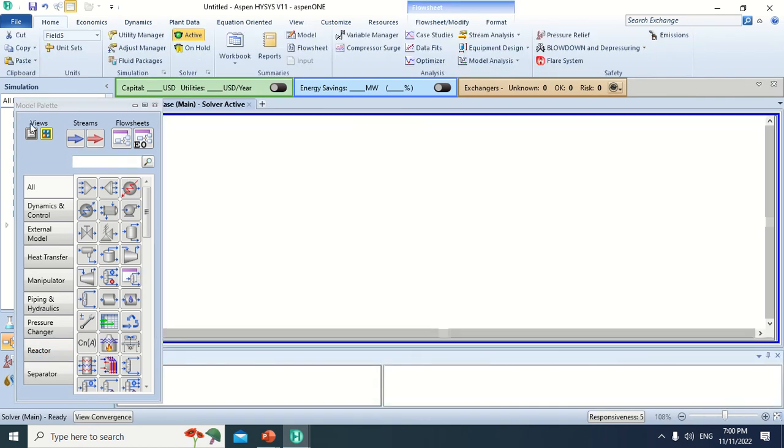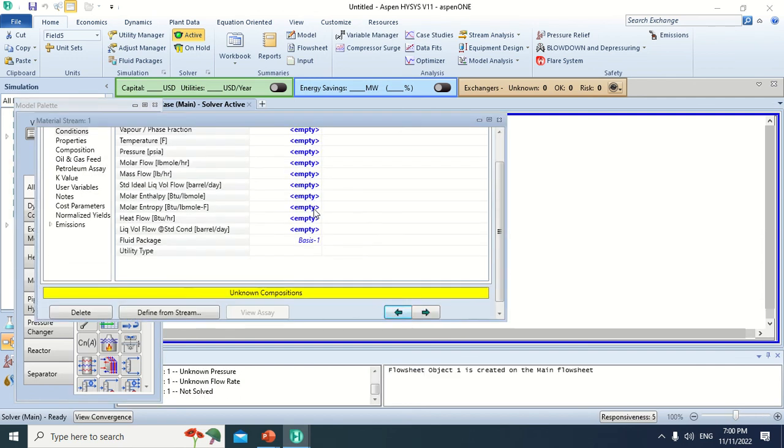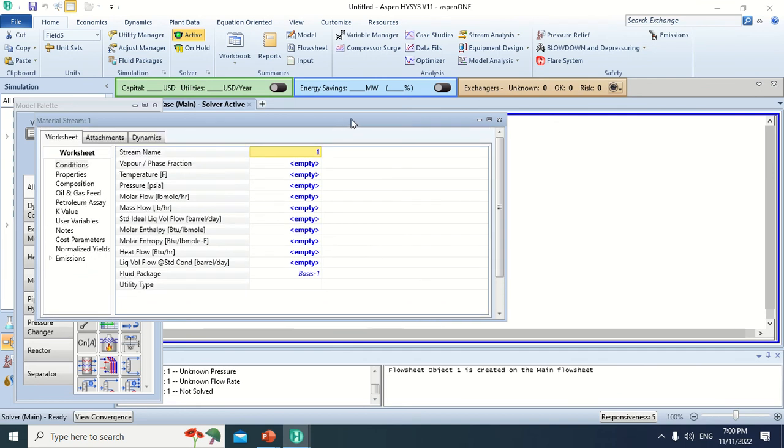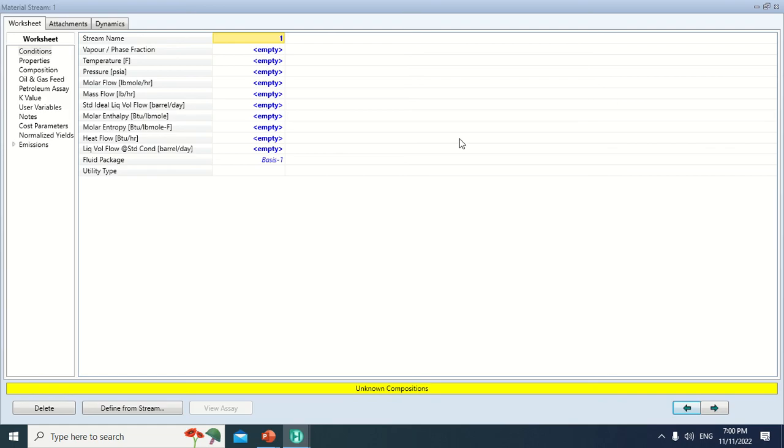Yes, and now I choose material stream. Click on it, and yes, I write the name for this stream and add and enter temperature, pressure, and molar flow.